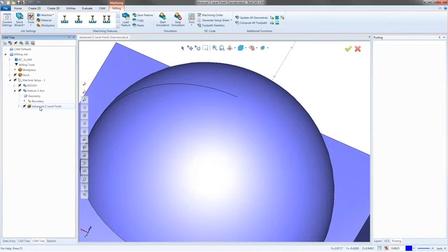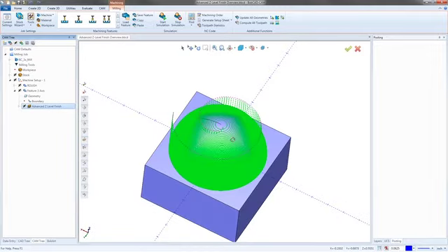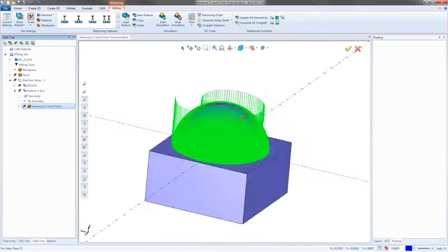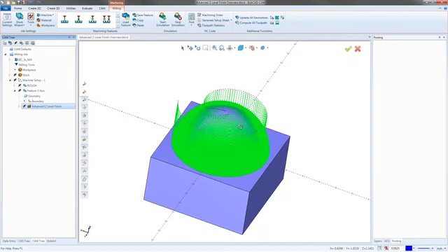So here's the toolpath now. That's where it starts. And then instead of connecting straight over, after every pass it's going to lift the tool, rapid to where the next pass is 1/8 inch away, and then connect those all with a rapid. So it looks nice. The only problem I don't like is there are a lot more rapids happening. The tool lifts up after every cut, moves to its next position, plunges down, and makes its cut. So there are a lot more rapids in here than I might want.